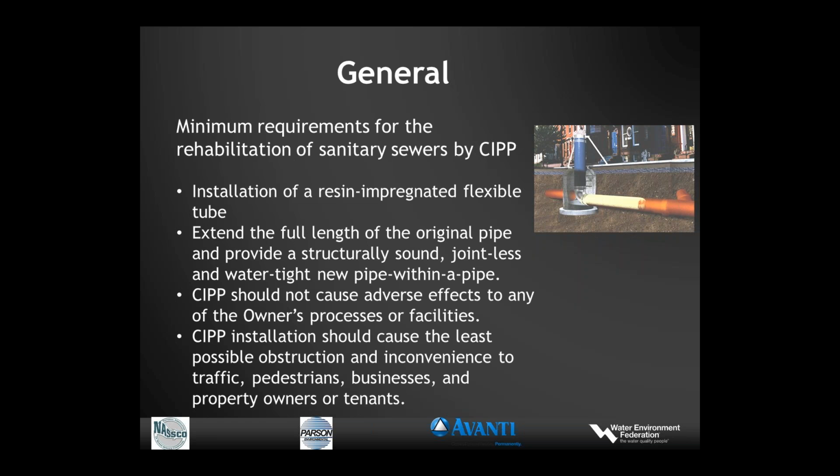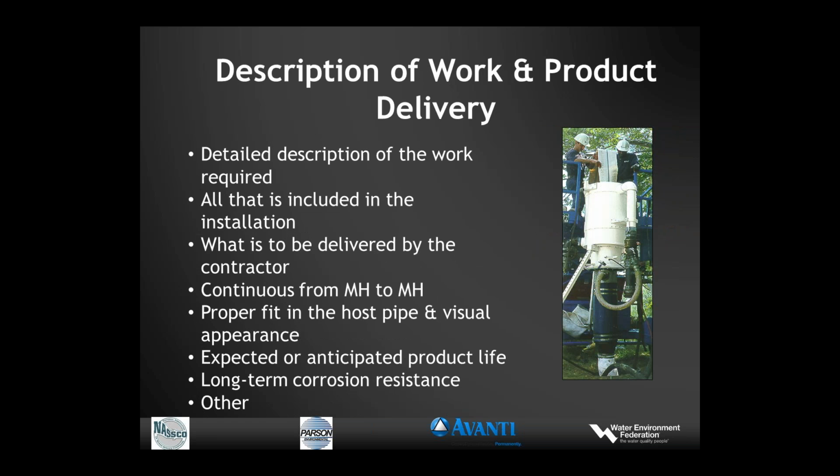In performing this and installing this product, neither these activities nor the finished product should cause any adverse effect to the owner's processes or facilities. None of these activities should cause materials to be discharged down the sewer that might clog a sewer or flow into the treatment plant. The CIPP installation should cause the least possible obstruction and inconvenience to the community. Not quite out of sight, out of mind, but that would be the objective.